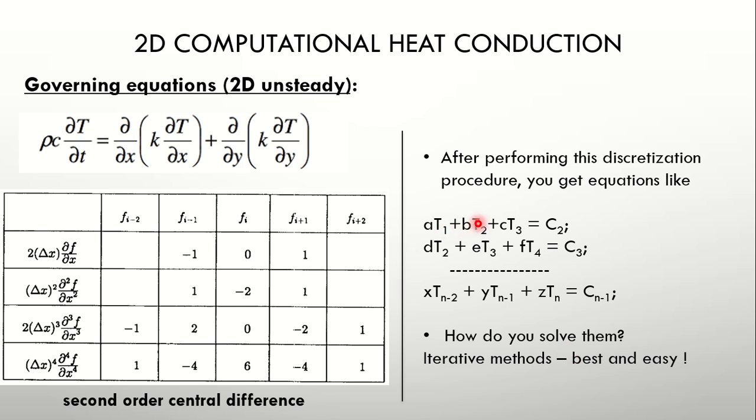So assume the temperature at n plus 1, where you are trying to find out. Initially you assume it to be the same as the temperature at the nth time step, and then calculate T1, and similarly calculate T2. You know the updated value of T1 and T3. Okay, sorry, T3 you assume again at the previous time step. Then you go to the next iteration. So within a time step you will have multiple iterations. Once between two iterations the temperature gets steady, then you go to the next time step.